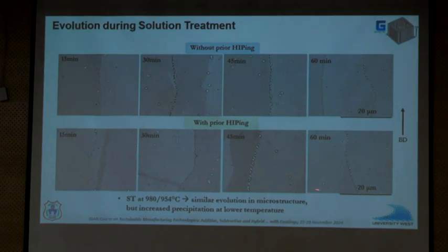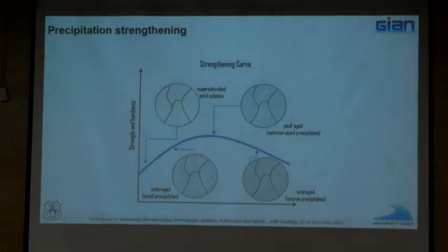In both of these cases, you begin to see grain boundaries, I mean delta phase decoration, at about 45 minutes. But there's not a big difference between 45 minutes and what's in the standard. So, no great motivation to look at solution treatment further. Let's look at aging.